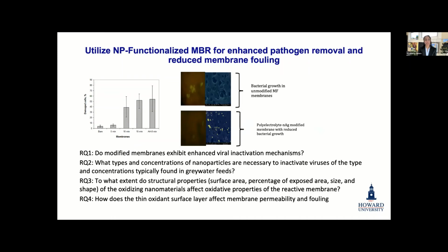So what we decided to think about was maybe coming up with a nanoparticle functionalized membrane bioreactor for enhanced pathogen removal and reduced fouling. This picture on the left shows some of our prior results from work in our lab over the years. In our lab, we've done a lot of work in general on reducing biofouling of membranes. For those projects, we put a nanoparticle on the membrane surface to try to decrease the buildup of bacteria on the surface, so you reduce biological fouling of membranes. And we showed that that was possible.